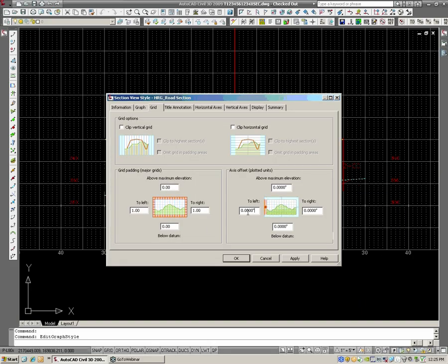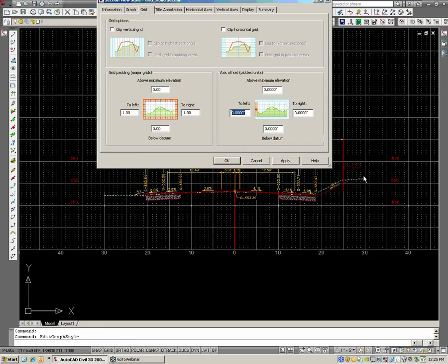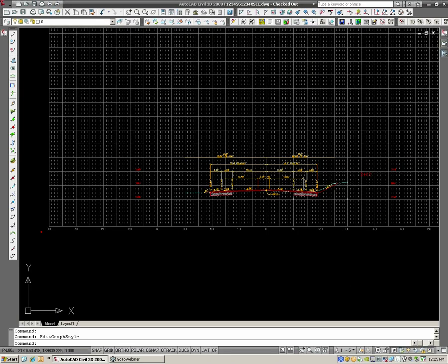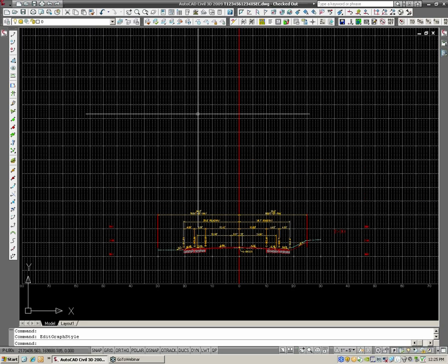And in here there's a padding. Basically this padding has to deal with these numbers. How far are they going to be away from where the sampling stops? So I'm going to make that a 2 for each of these. And you can see it will move out the text from there. So we can just keep doing that and going through.